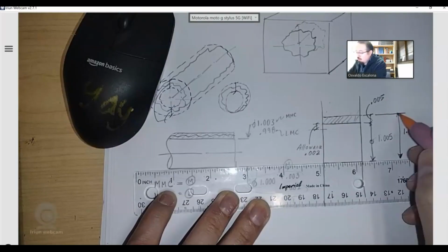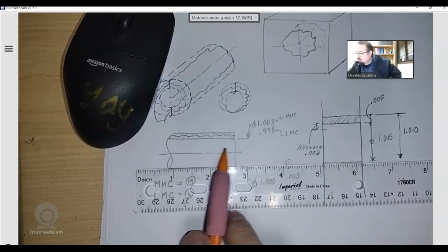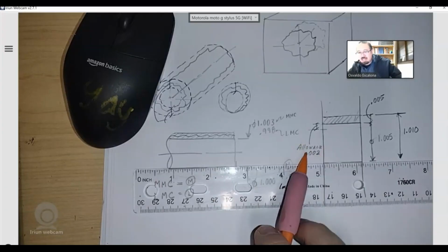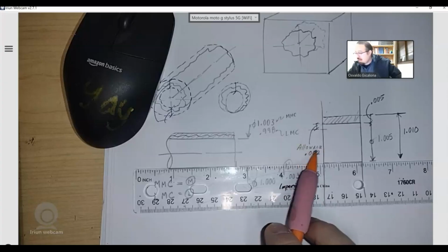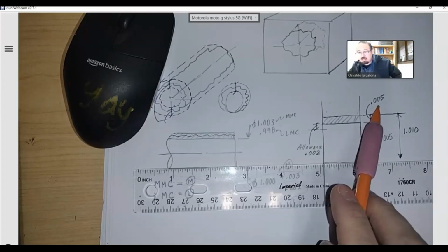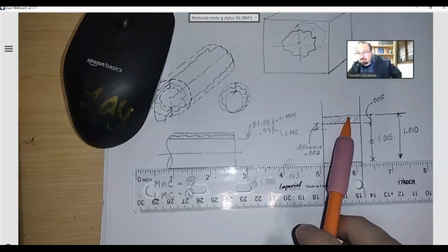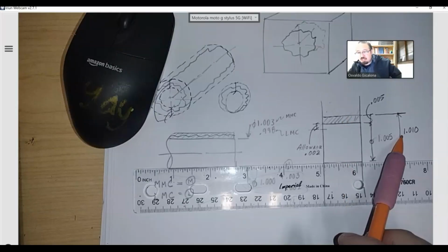Now, what's happening right now? I am grabbing that pin, and I'm able to put it inside of the hole. It has a little bit of wiggle room. I can determine the diameter of the smallest hole, and I give it a little bit of tolerance to allow some wiggle room for the manufacturer, and that allows me to determine the maximum size of the hole.